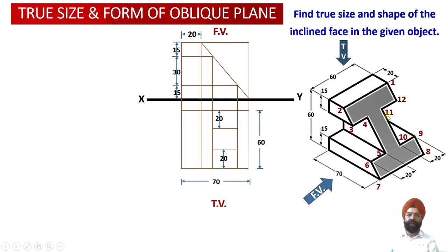So in the top view, I had obtained these thicknesses from the front view projection. So this is the thickness of this particular inclined web. This thickness of this inclined web has been projected corresponding to the points which we had obtained from the view. So this is one projection corresponding to this particular part of the web.